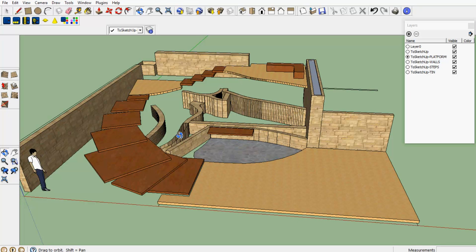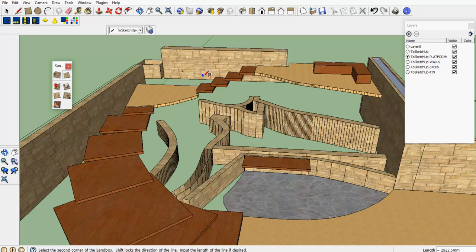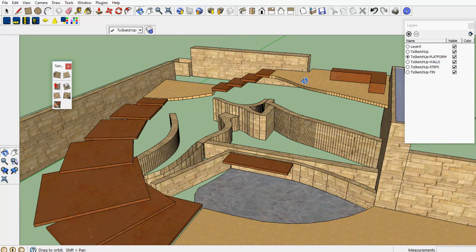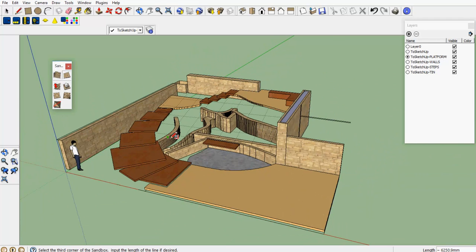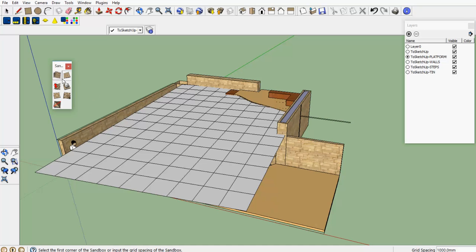We'll use these sandbox tools over here on the left. Let's float the little toolbox, and I think what we'll do is set a mesh across at that top level, and to do that it's create from scratch. And I think if we run from, say, that point there across in this direction, we'll just need to amble around a little and then go back to here and to there and across to there, and then you can see that the mesh is extending out, and as long as we cover that part of the site, I think we'll do reasonably well.